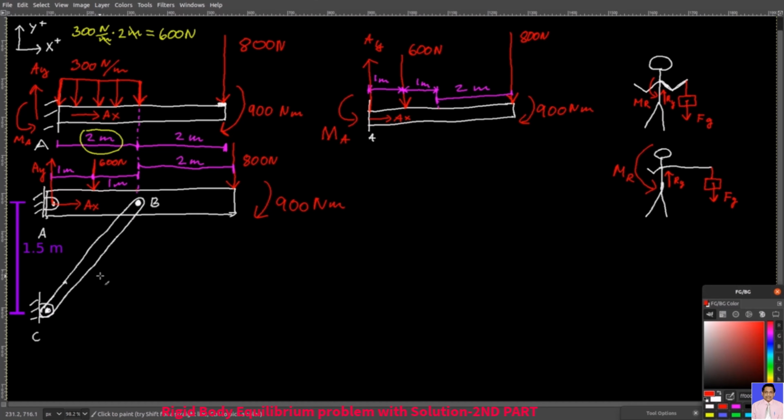You will compensate for that by using a rigid rod that is connected to the beam at B with a smooth pin, and then the other side of that rod is connected to the wall at C, also with a smooth pin. So these will be your reaction forces, Cx and Cy. This rigid rod, BC, is called a two-force member.